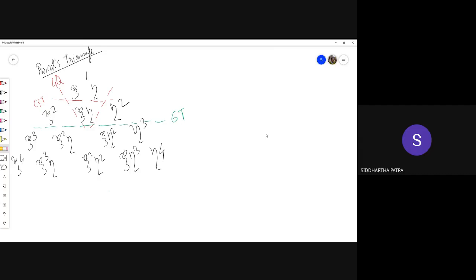Now quadrilateral elements. When we had the linear element, that would be linear in both xi and eta. When I'm directly drawing the quadrilateral in the natural coordinate, I'm no longer drawing in the physical coordinate. So this one is -1, -1, this one is 1, -1, this one is 1, 1, and this one is -1, 1.